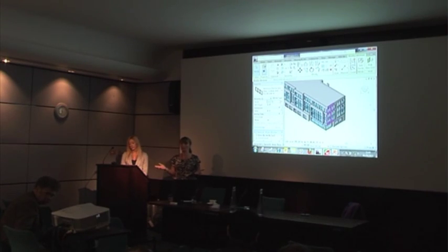The other issue, which Michelle touched on, was the fact that there's no standard approach in how people use these BIM tools. So you've got complete flexibility to build that model in any way you see fit. You can use walls to be roofs or whatever you want to do. And we can't legislate for all of those possibilities using the GBXML import, because it is fairly simplistic in the way that it deals with things.